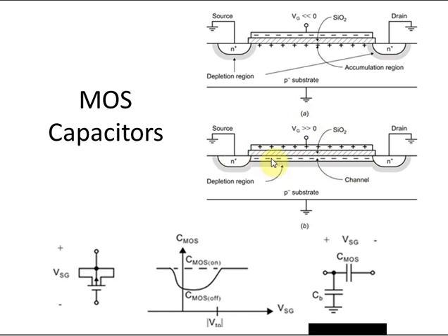So clearly what you have is a situation where the capacitance of this MOS device is a function of the gate voltage. Now, that can be desirable in some applications, because what it means is that you can realize a varactor, a controllable capacitor, which can be a very useful building element for tuning circuits. On the other hand, it's not going to be very good if linearity is very important. Again, it's a nonlinearity because the capacitance or the impedance is changing as a function of voltage. It's going to distort analog waveforms, and so that's the problem when high accuracy is important.